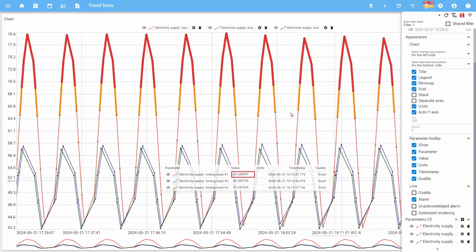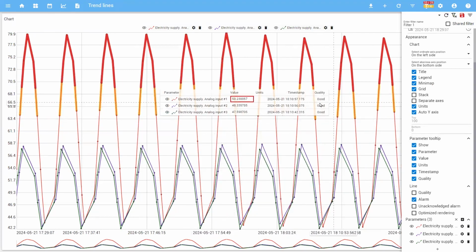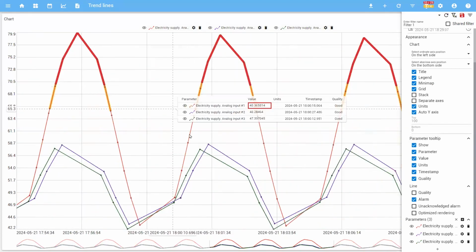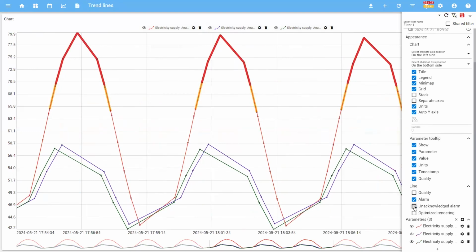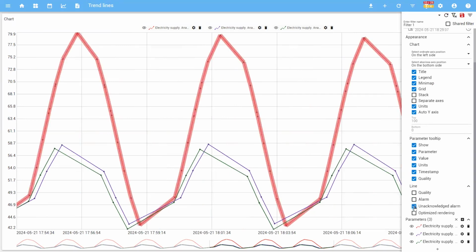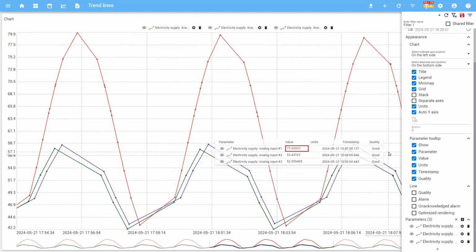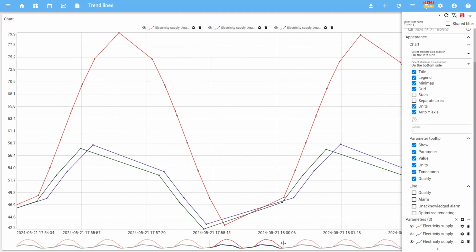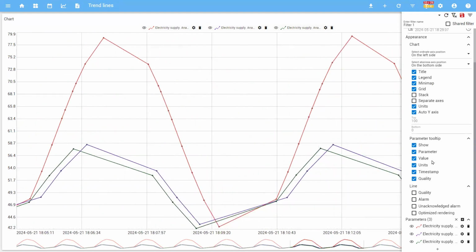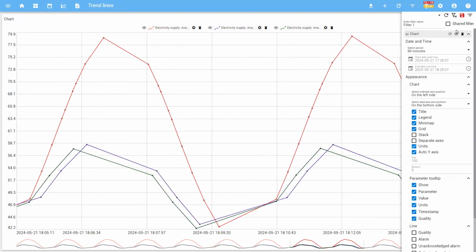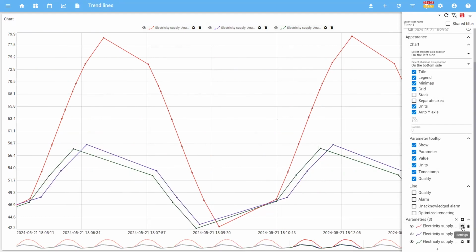At the same time, one interesting feature that I like is the one that I'm showing, the alarm. You highlight, basically, you zoom in and you zoom out, of course, and you can even make it possible that you select only the alarm or the unacknowledged alarm. So on the trends, this will be visible in a very nice way. Now, all the settings that you see right on the right side, this could be done as a group, right, for all the parameters, all the signals. But at the same time, after you save it, it could be done for individual signals, right?